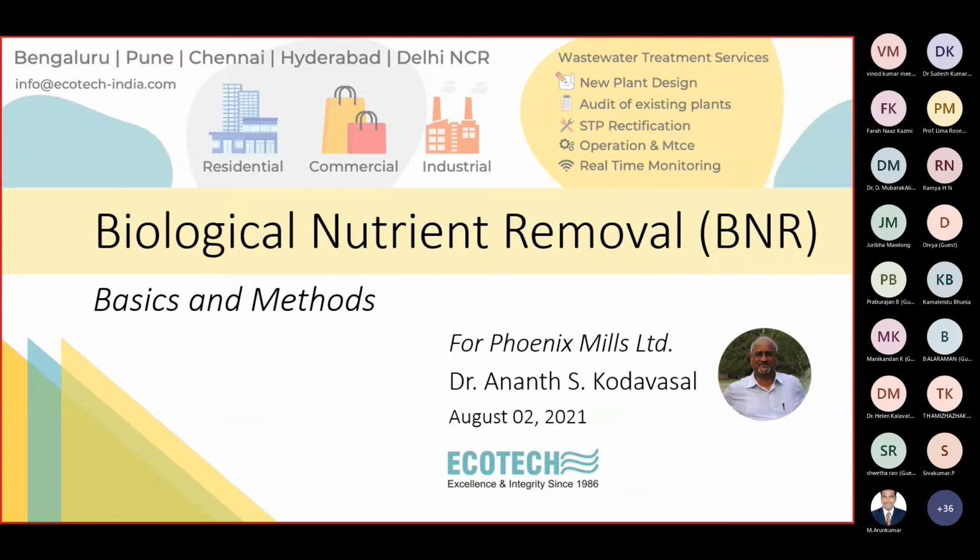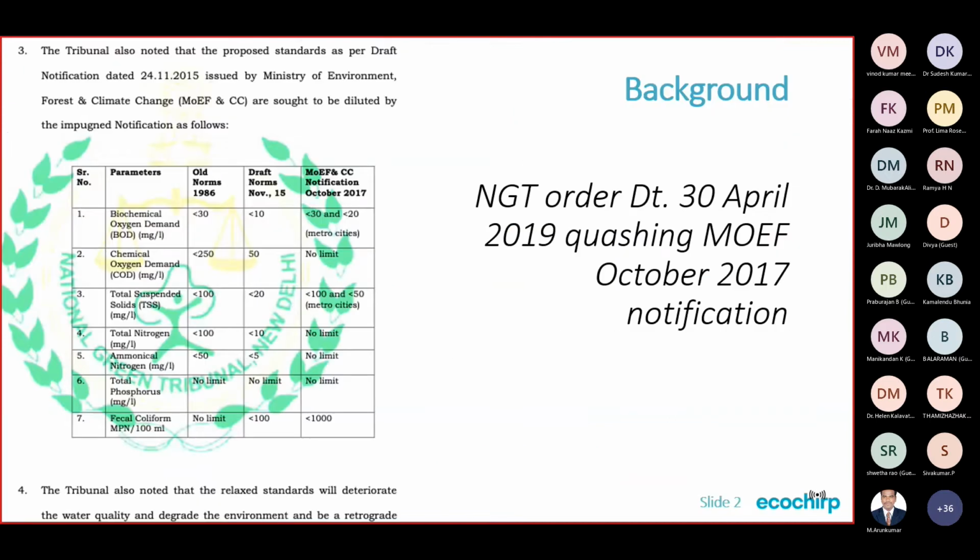So this is how we do it. And it is extremely difficult. If you see, many of the STPs in residential, commercial complexes, in fact, in this mall itself, are in the basement. Space is limited, space constraint is there. So we have to find ways and means of retrofitting a denitrification stage. So this is one of the methods. This is what we use. The technology used is the MLE process.